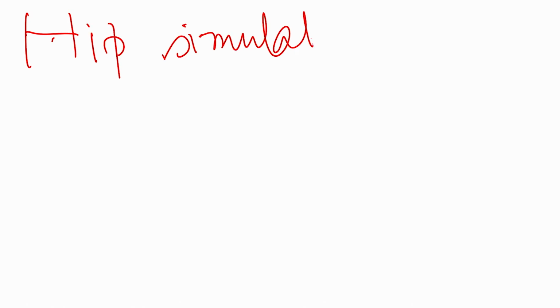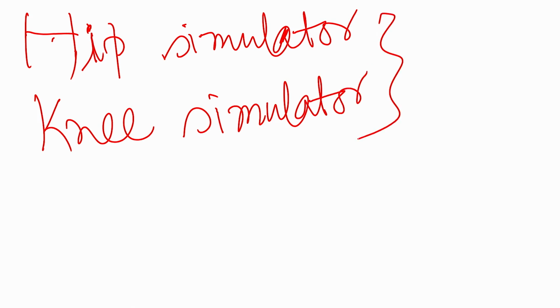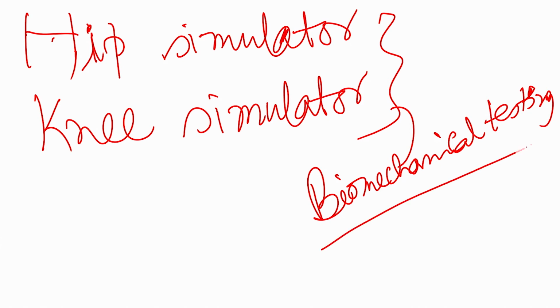They are called bio-tribometers, the more important ones being the hip simulator and the knee simulator. The hip simulator not only simulates the biomechanical stresses but also the gait cycle. These are the most important tribological or biomechanical tests, where long term fatigue wear properties of implant materials can be evaluated, and this is used in preclinical studies.